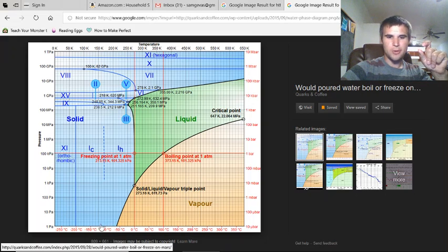In order to increase the temperature 1 degree, it takes a certain number of BTUs. The last degree that you go through, where the phase change actually takes place, requires significantly more BTUs, because the phase change demands additional energy.